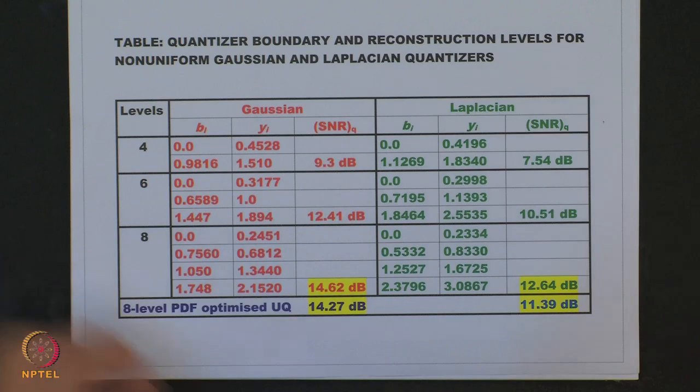Okay. Now, again the question is how good are these quantizers? These are quite good quantizers provided we have a good knowledge of the PDF of the input with all its parameters. So, the same comments which we made for the uniform quantizer with non-uniform PDF hold good. There could be mismatch. The mismatches could be that we know the PDF of the input but are not sure about the variance, or we choose a wrong PDF itself. In both the cases basically the performance deteriorates.